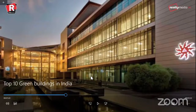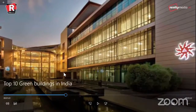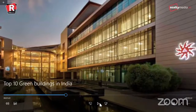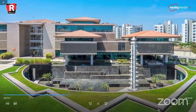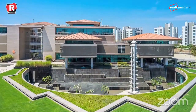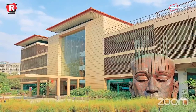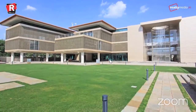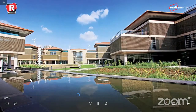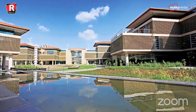Now Suzlon makes windmills themselves, so renewable energy is their main motive. It is a building which is GRIHA 5-star rated and IGBC Platinum rated. It is also one of India's first buildings to be LEED (Leadership in Energy and Environmental Design) certified. Renewable resources: the campus has 18 hybrid wind turbines that fulfill 7% of the total energy consumption. The rest of the energy demand is met from off-site wind turbines. The structure is designed to ensure maximum daylight exposure, thereby reducing artificial lighting consumption.